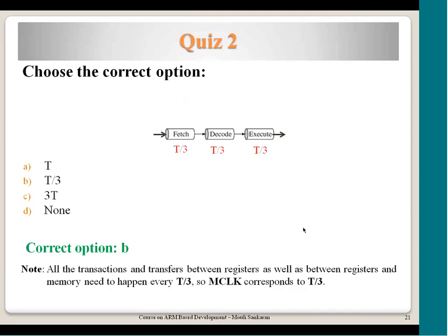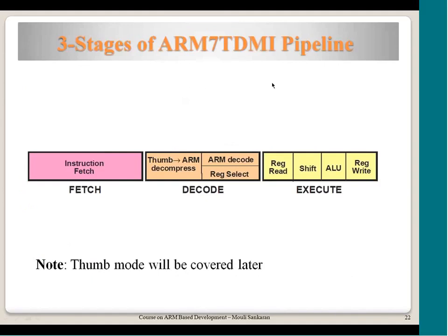Now just to summarize what is happening in an instruction pipeline, this is a fetch stage. Decode understands what the operation to be performed is and which registers are to be selected for the operands. During the execution stage, as I mentioned during the Dataflow explanation, registers are read, the A and B buses from the register file are read by the ALU, the barrel shifter performs the shift or rotate operation, and the ALU performs any operation that needs to be done on the two operands, Rn and Rm, and the Rd gets written into.